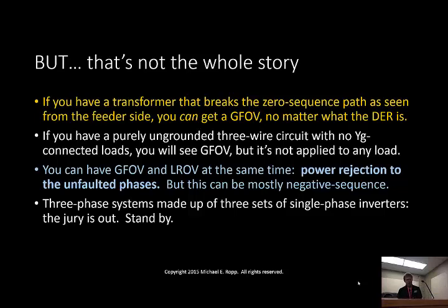I've got one bullet here on the bottom that we're not going to talk about a lot today, but there's still some question about if I have a three-phase system that is made up of single-phase inverters. In some ways, single-phase inverters making up a three-phase system are better. Let's assume for a minute that I have a three-phase system with single-phase inverters connected Y, like they're connected phase to ground. In that case, what's going to happen when I have my phase C fault? The phase C inverters are going to see an undervoltage and drop out. Phase A and B inverters are going to keep chugging merrily along.